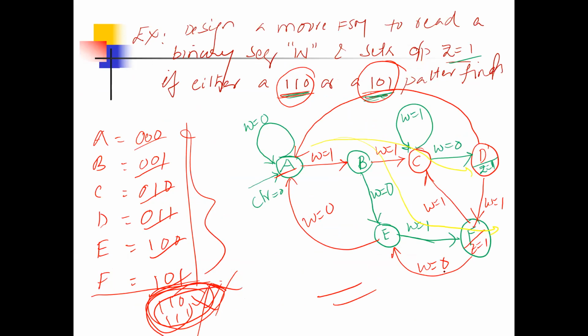Here there are two sequences, and if either one is valid, it becomes one. So we start to draw the state diagram. With the state diagram, the states can be assigned binary codes. You should confirm whether all the combinations are used. If any combination is left, then definitely a default case is required.